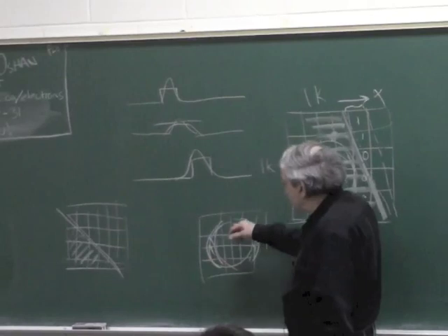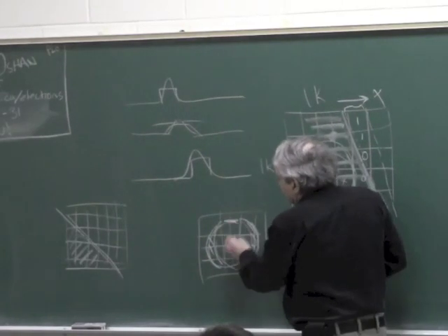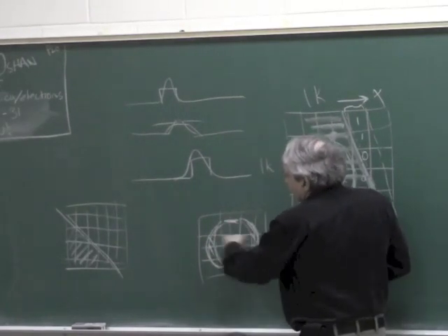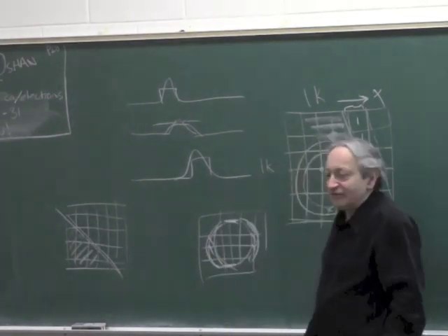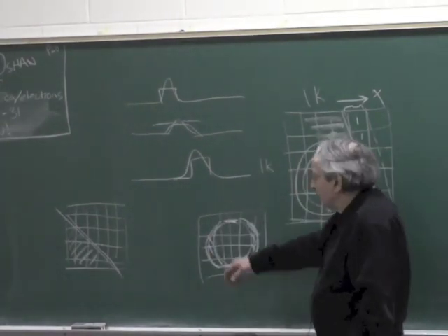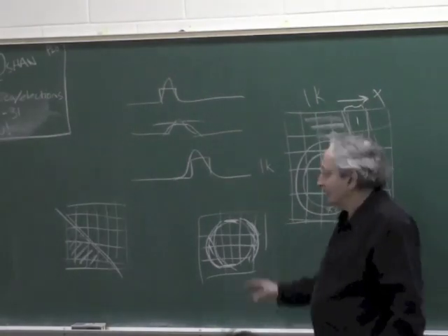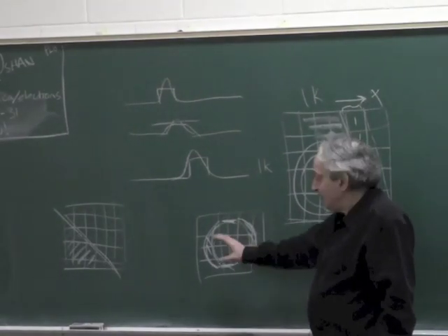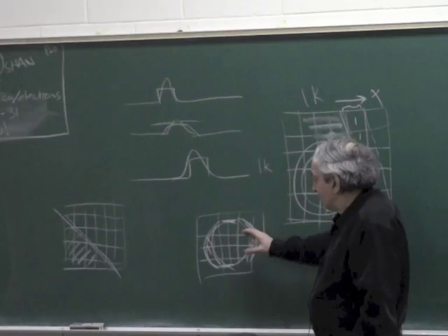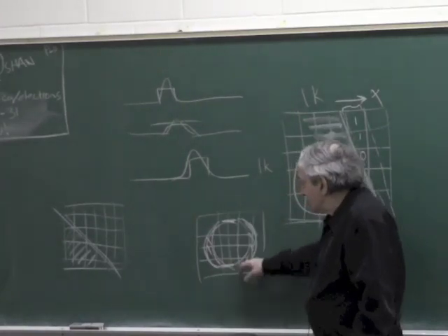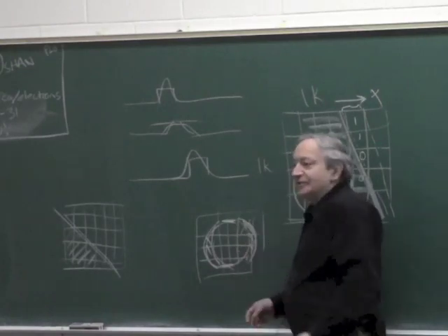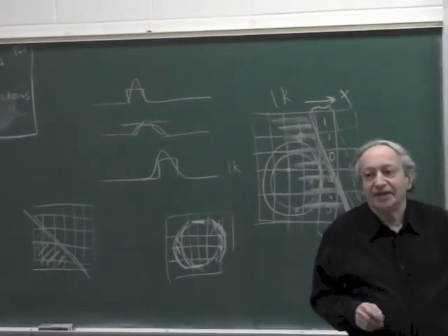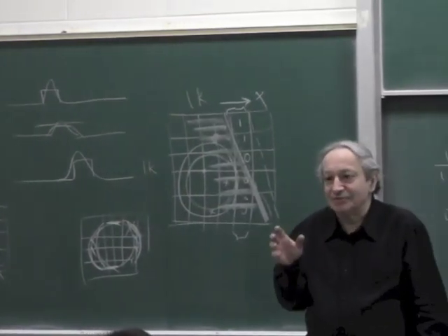Some pixels will be less effective, like these pixels here if it moves this way, but you have a lot of other pixels. So if you have a circle which is maybe 250,000 or 500,000 pixels out of 1 million, any movement of 1 pixel will cause thousands and thousands of pixels to change states. So dust wouldn't matter, and you get very, very high accuracy from the slightest movement.